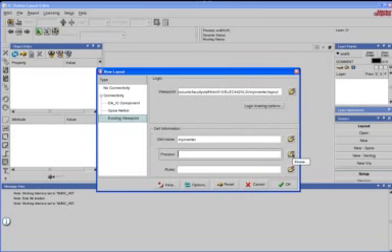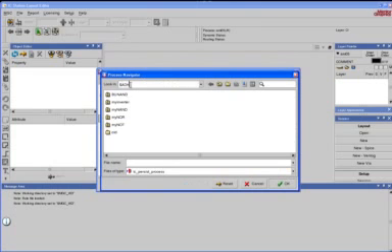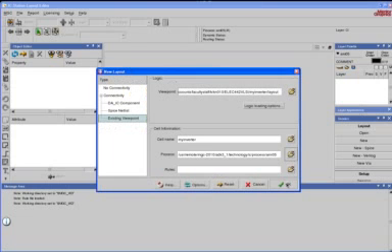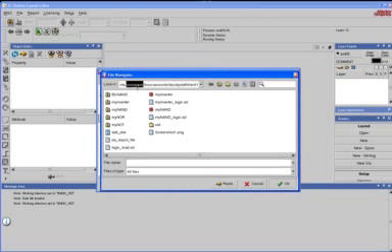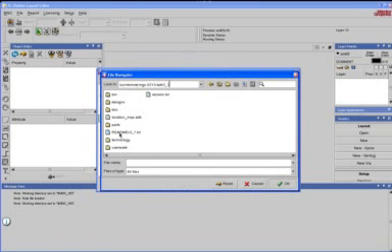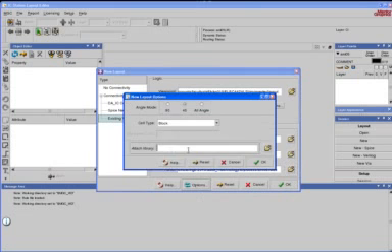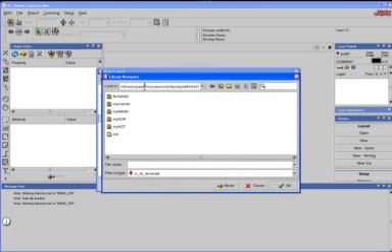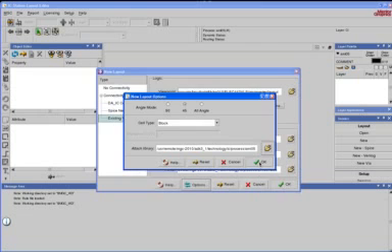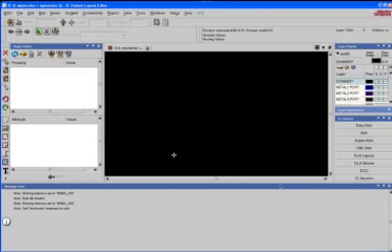On the process, click on the browse button, adk_. That will take you to technology, IC. Click on process, AMI05, say OK. Under rules, you go to the same adk, technology, IC, process, AMI05.rules, say OK. Click on options, attach library. Let's click on browse. Again, same $adk, technology, IC, process, AMI05. Say OK. Say OK.